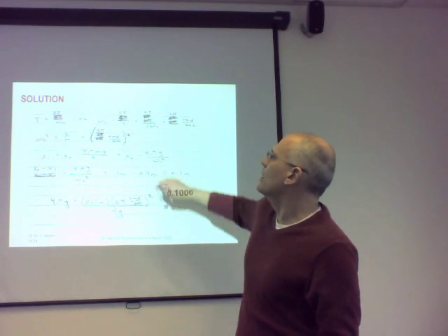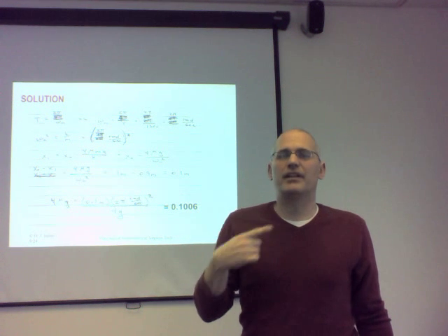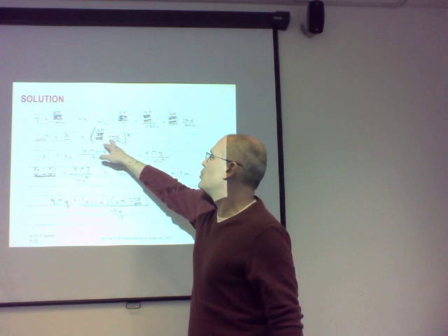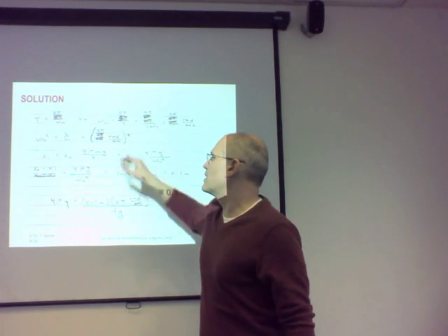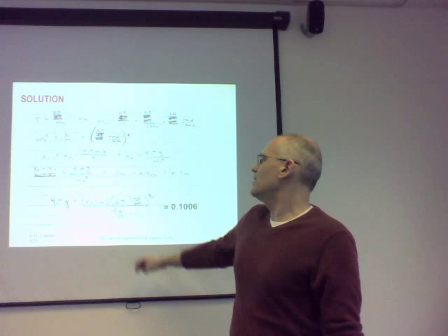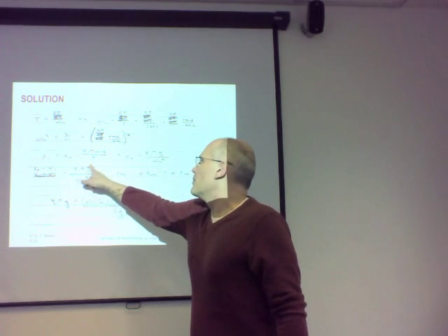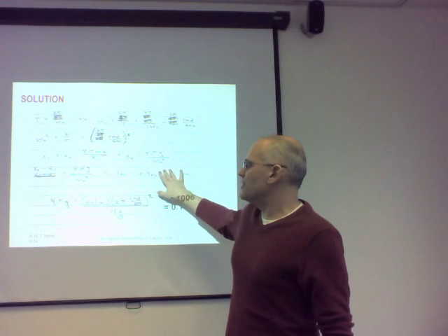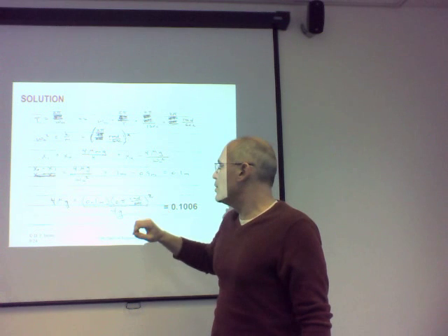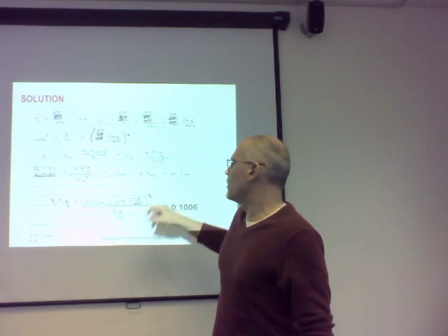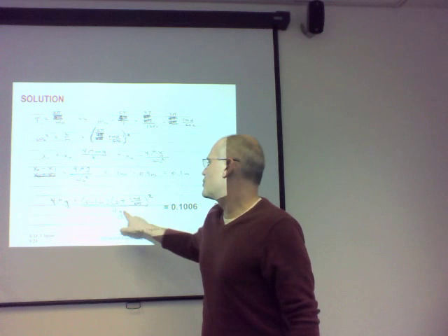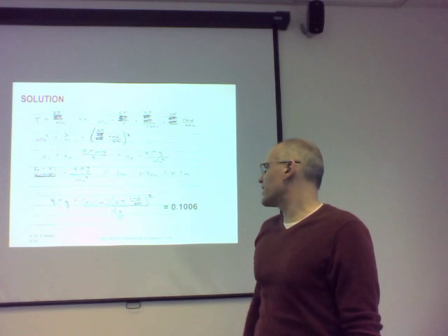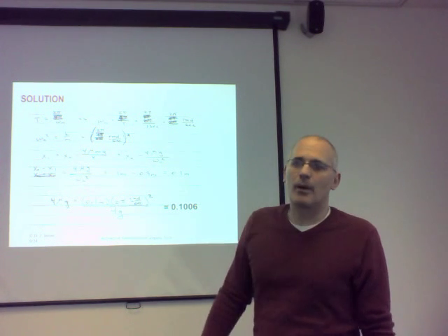What's omega n squared? We can get that from the period. We know the period is 1 second. So our omega n squared is going to be this 2 pi radians per second, whole thing squared. So 4 mu g over omega n squared is 1/10 of a meter. We can rearrange this term and solve for mu. So mu is going to be 0.1, divided by 4g, so multiply by omega n squared, 2 pi radians per second squared. And we get damping of about 0.1.